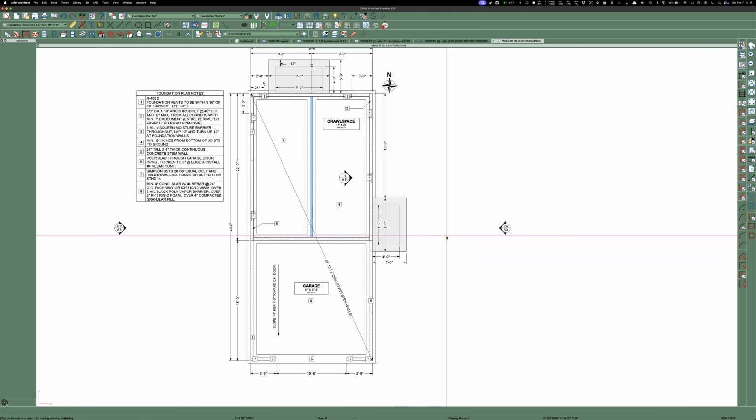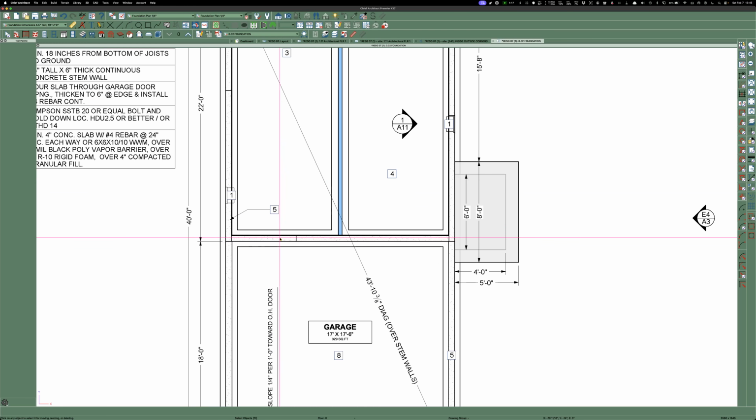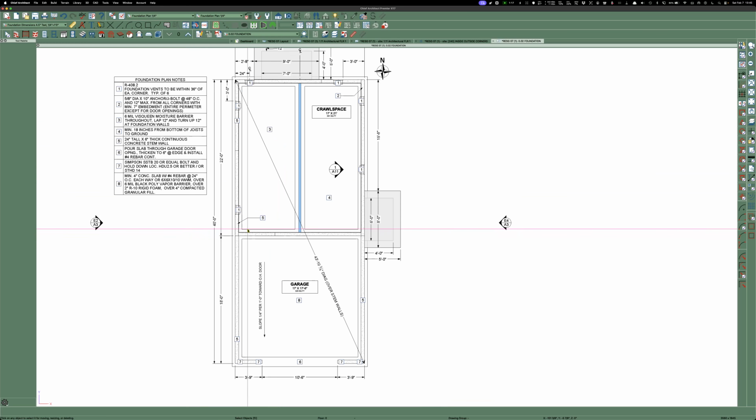And don't just set your default to be to the nearest inch, because I've seen that and it kills me. People will just drag a wall and all of a sudden they'll think it's right. But then if you highlight the wall and you see this 22 and you click on it and it's 22.0165 whatever, then you're not exactly 22 feet. The software is saying you are, but you're lying. What you would do is highlight that long number and just type in 22 feet, and it will adjust where this wall is to the proper dimension.